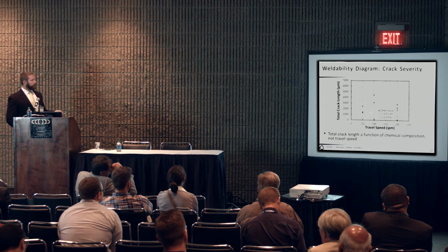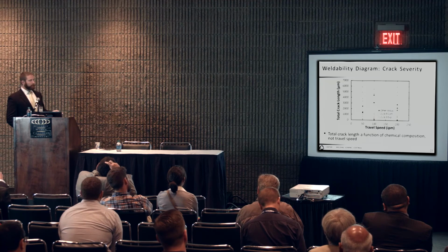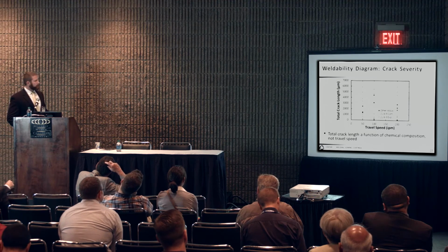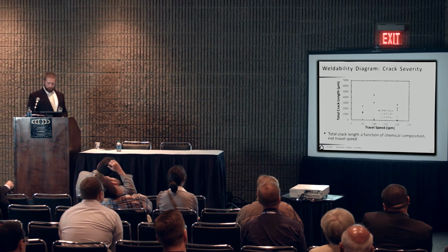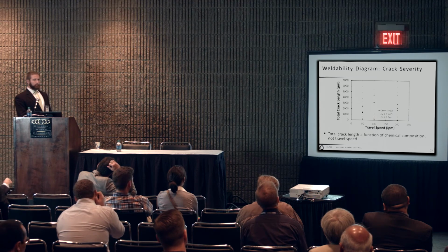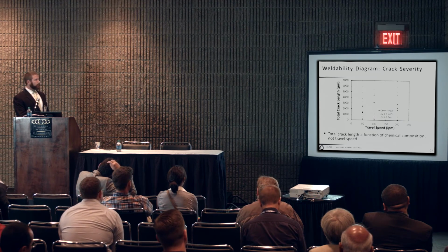Interestingly, out of all the 14 2169 commercial heats, only one of them exhibited cracking behavior. We had one alloy that shifted to primary austenite at 100 and 200 inches per minute and showed cracking there. But even some of the other commercial alloys that showed primary austenite solidification had no cracking observed.